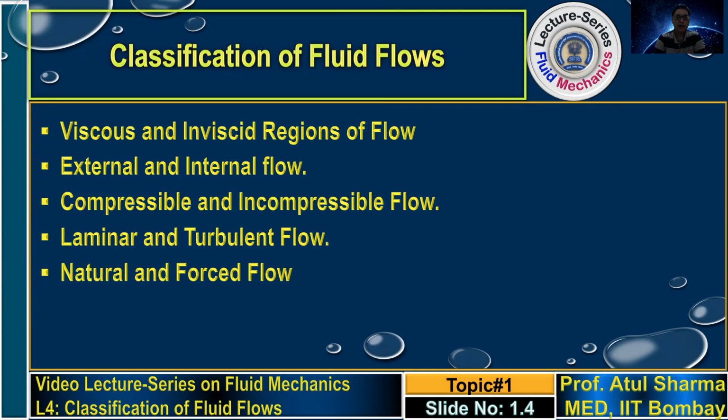Whenever there is a fluid flow, it depends on whether we need energy to get that fluid flow; then it's a forced flow. Whereas many times under natural conditions also, like if an object is heated, buoyancy naturally comes into this problem and you have a buoyancy induced natural flow. Whereas for forced flow, we need a pump or blower to generate the flow.